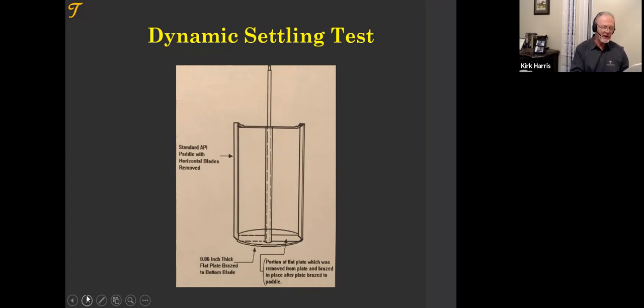Once the desired temperature and pressure conditions are reached, continue stirring at 150 RPM for 10 minutes to be sure to condition the slurry. Reduce the stirring speed to 25 RPMs to maintain the final temperature and pressure conditions. Observe for at least 30 minutes is what we'll do. And then we'll cool the machine down and we'll pull it out.